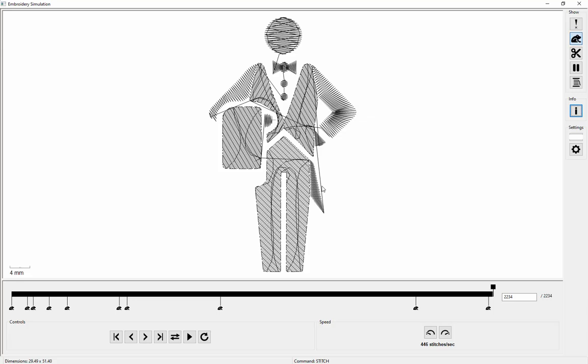But even beyond that, if I was stitching just one of these and we had all these thread jumps, my machine would look at these thread jumps and it would do a thread trim at all those positions, right? But we wouldn't necessarily want that because that is not very production friendly.